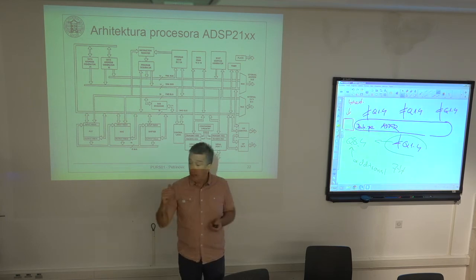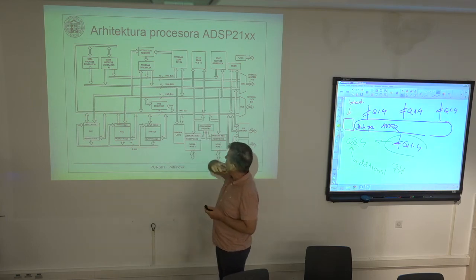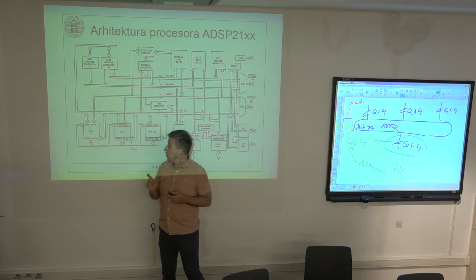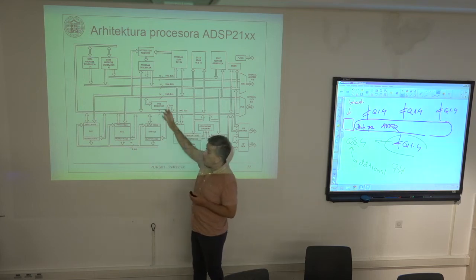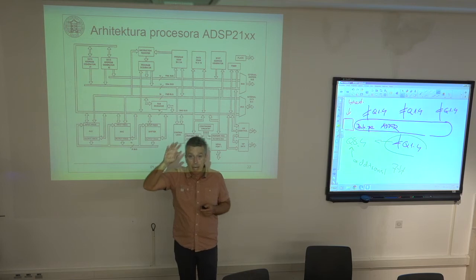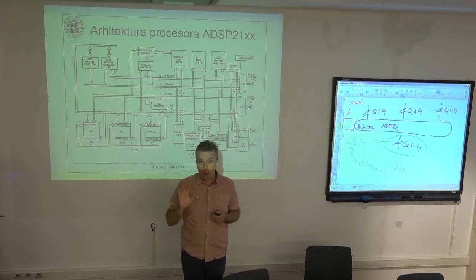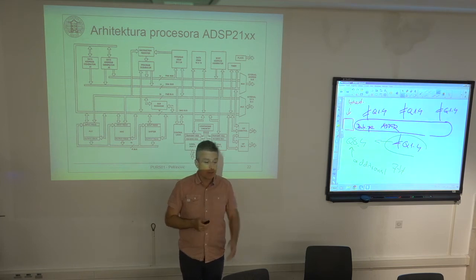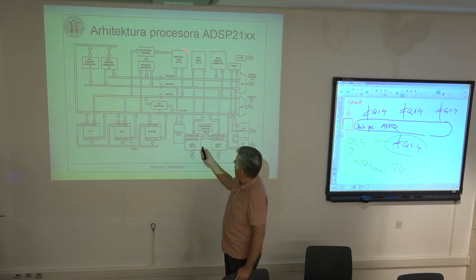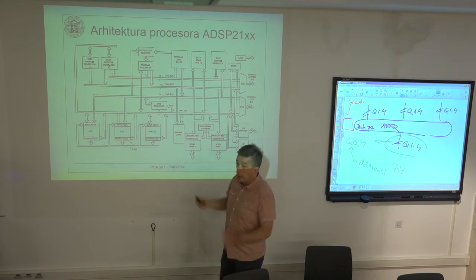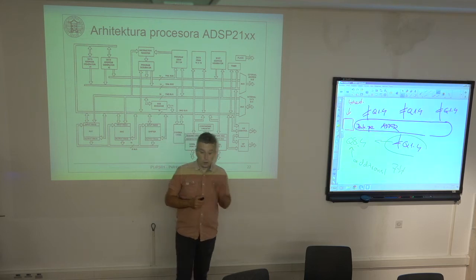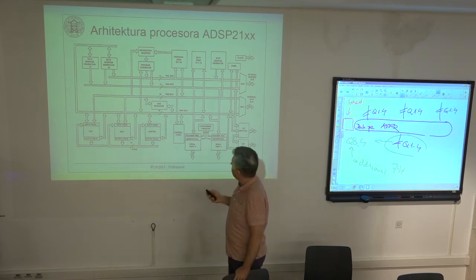So this DSP has an instruction of 24 bits wide, but if this program memory is used for data storage, only the 16 uppermost bits are used, only the topmost 16 bits; the last 8 bits are ignored. They are used only in the case I interpret this value as an instruction. If I interpret this value as a data value, only those 16 most significant bits of the 24 bits are used as a data value. Okay?